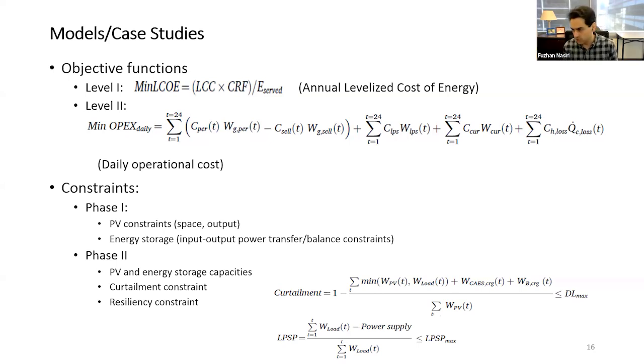we're going to be experiencing shortage. It is called loss of power supply. So there is demand, but this demand is unmet. The percentage of time that we have those situations, we're going to bring to a minimum. It cannot be 0 because there could be moments that we absolutely need to switch to grid, but there are moments that we don't need to switch to grid, so we want to minimize that sort of shortage. Even if we switch to grid, we might end up with shortage because at the time we want to buy from the grid, there is not enough access for us.